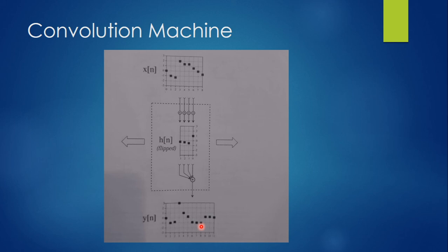Today we have discussed the impulse decomposition, and based on the impulse decomposition what we have is the convolution sum. And the importance of the convolution sum lies in the fact that if you only know the impulse response of a discrete system, you can find the response of that discrete system due to any arbitrary inputs.